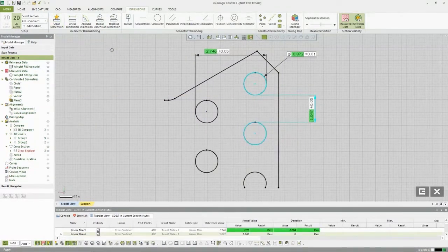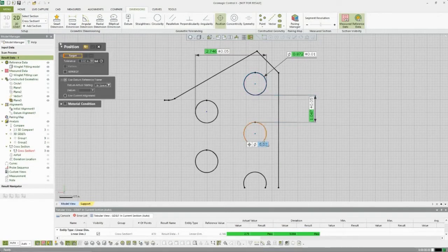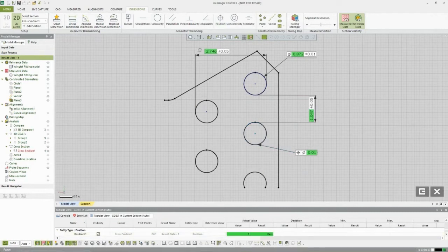Okay. Same rules apply as well, GD&T, so I can do a true position. So let's say we do it on this guy. On any change to our dimension, you can apply that there. So any of the stuff, or most of the things you can do in 3D, you can do in 2D in any sort of cross section.